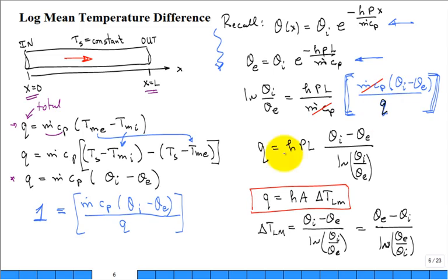So the total rate of heat transfer is equal to a convection coefficient, an area, and then some appropriate temperature difference that drives that heat transfer. And they call that the log mean temperature difference. Again, it's the appropriate temperature difference that drives the heat transfer. It's from the pipe into the fluid. And this equation works regardless, if, let me see if I can draw it like this.